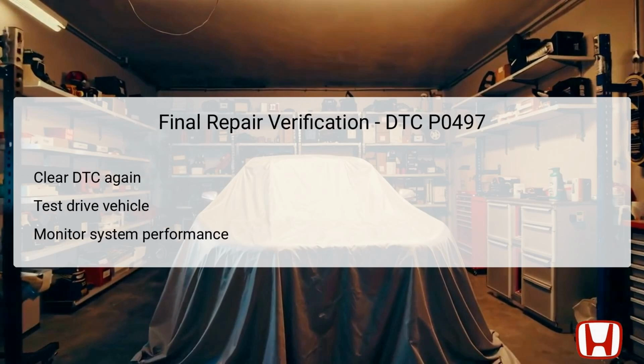After completing the troubleshooting steps and making any necessary repairs, it's essential to perform a final verification. Begin by clearing the DTC using the HDS once more. Then, take the vehicle for a test drive to ensure it operates smoothly without triggering the DTC again.